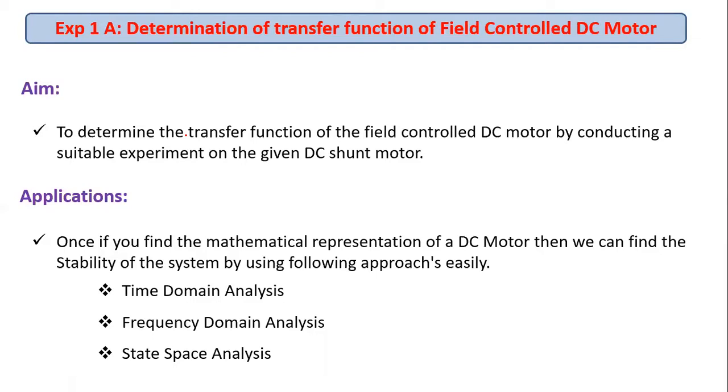Coming to the elasticity, the machine is made up of cast iron or cast steel, which doesn't have the elasticity property. So no need to consider the spring. In mechanical rotational system, we are taking moment of inertia and friction only. Coming to the electrical parameters, we are having the field winding resistance and field winding reactance. In the same way, coming to the mechanical system, here we are having only J and B, moment of inertia and friction.